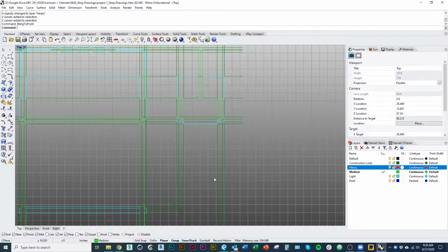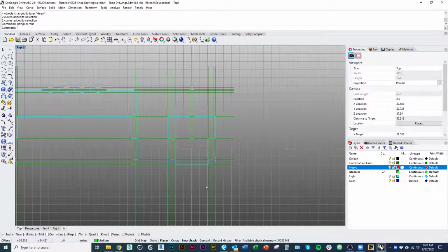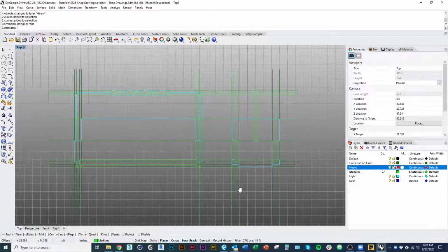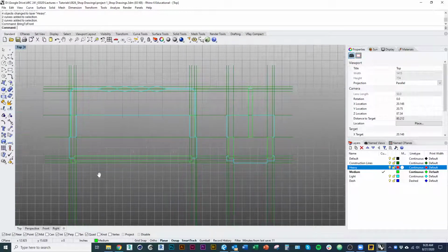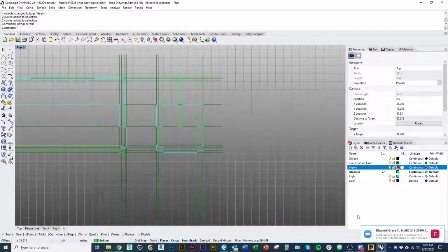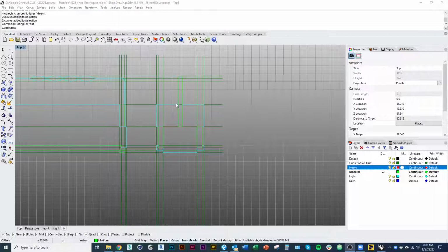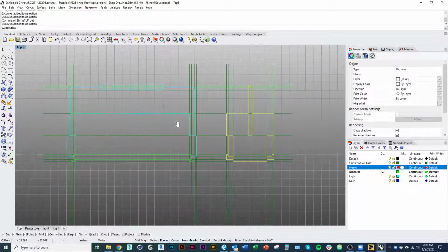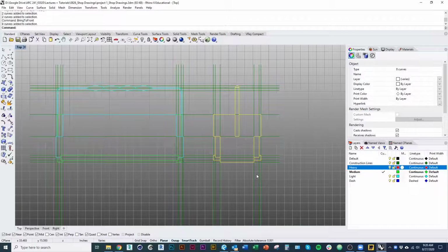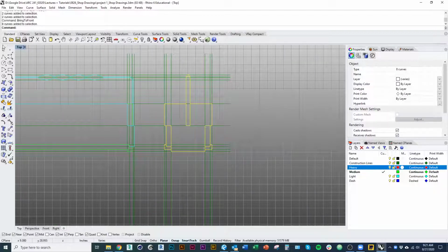Okay, so working from that assumption, I'm going to draw a section. So we have 2 elevations here. That fulfills the requirements, but we also need to draw two sections. So an easy way to draw two sections is to start by copying the existing elevations we have here, because we already know that those dimensions are right and because we're in the right projection and so on. So what I'm actually going to do is draw another line.